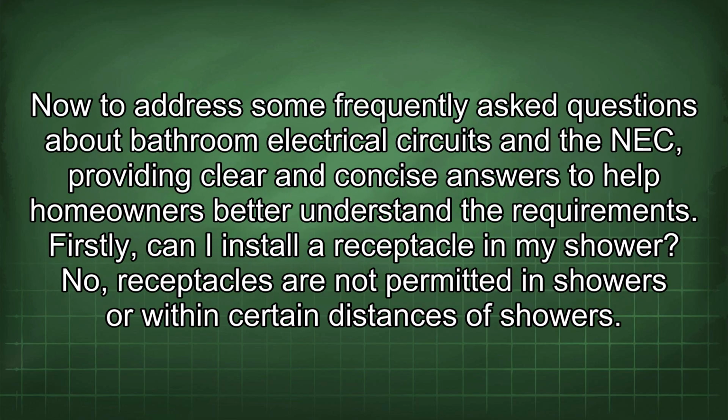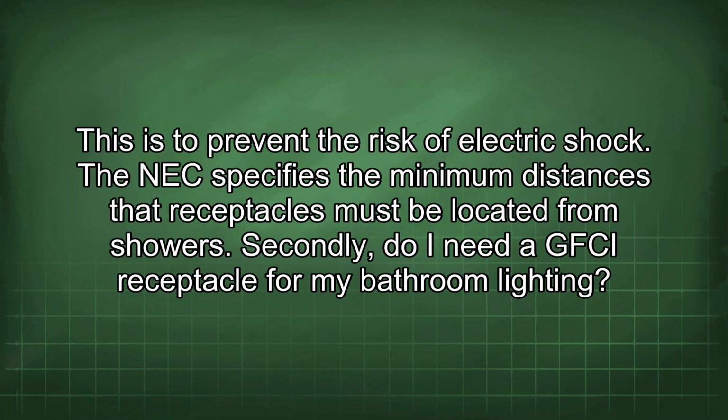Now to address some frequently asked questions about bathroom electrical circuits and the NEC, providing clear and concise answers to help homeowners better understand the requirements. Firstly, can I install a receptacle in my shower? No, receptacles are not permitted in showers or within certain distances of showers. This is to prevent the risk of electric shock. The NEC specifies the minimum distances that receptacles must be located from showers.